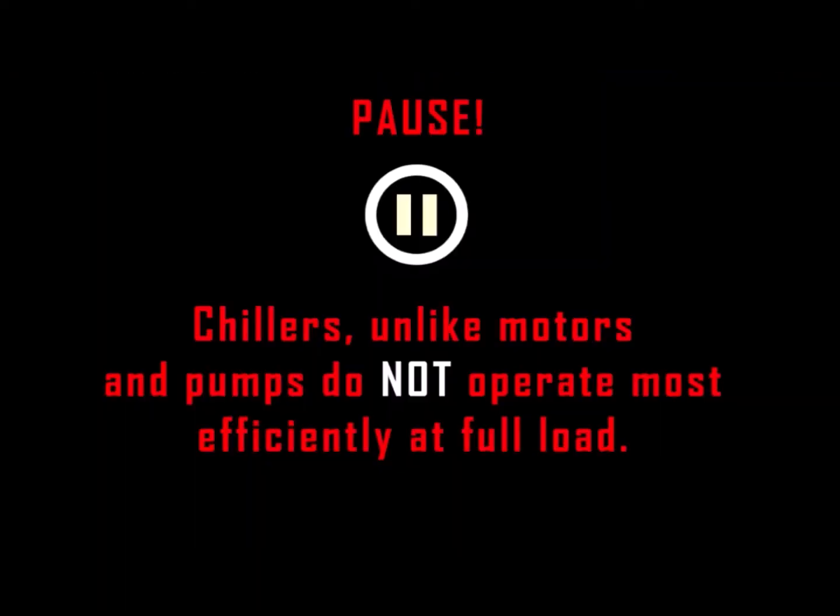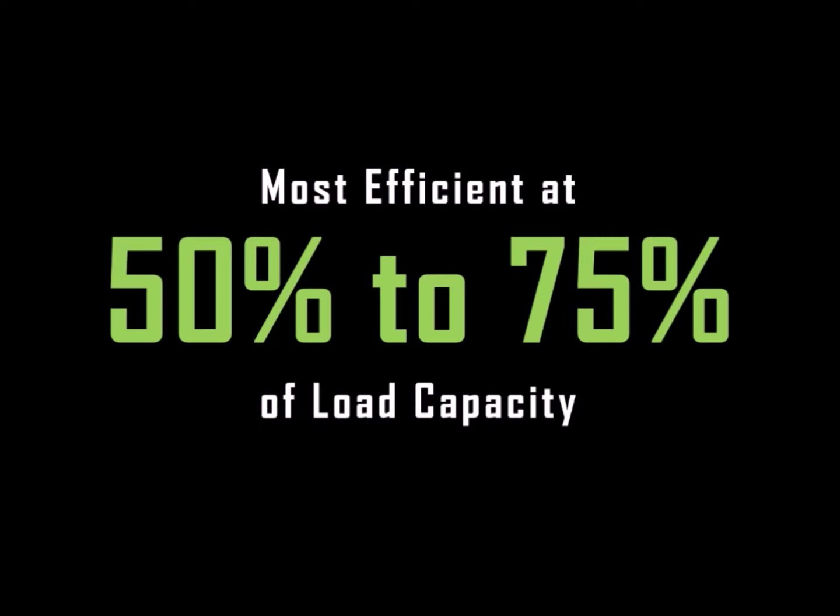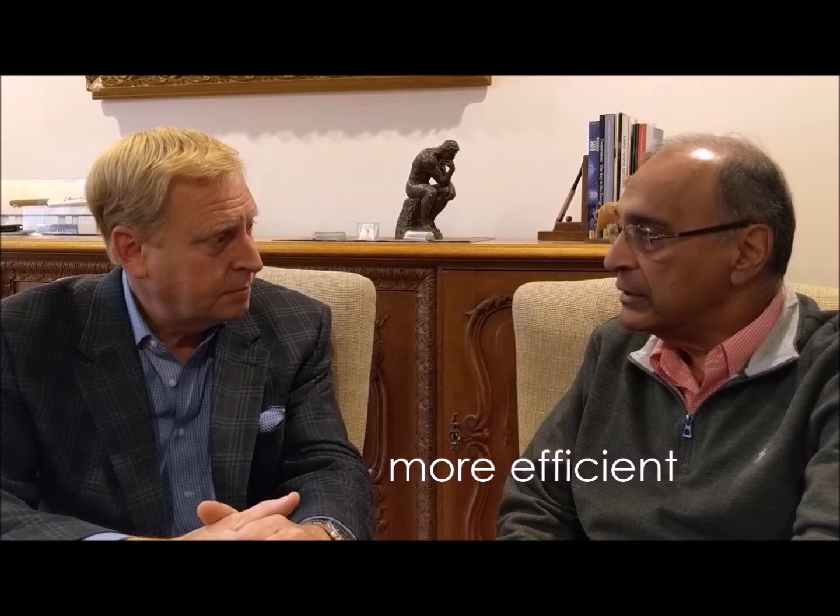No, balancing the loads is in fact one of the things we do, but the most important thing to understand here is that chillers, the chiller compressors, unlike motors and pumps, do not operate most efficiently at full load. If you have a motor, its maximum efficiency is when it's running at 100% load, even 101, 102% of the load. Similar with pumps. But with chillers, the efficiency curves are quite different. They do not operate most efficiently at maximum loads. They operate most efficiently at somewhere between, say, 50 to 75% of the load. So part loading the chiller makes it more efficient.